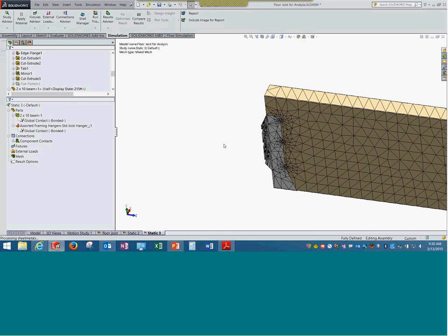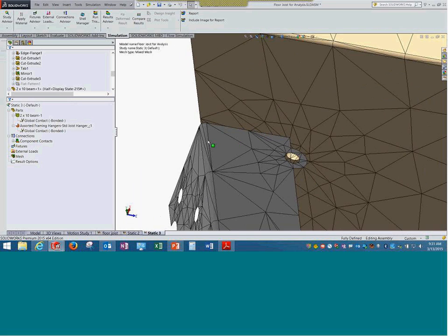Okay. So if you observe here, this part, which was actually a sheet metal part, the software has the ability to automatically convert it into a surface and mesh it with shell elements. You may not find this in any other software, wherein we are treating appropriate geometries appropriately in the simulation part of it.